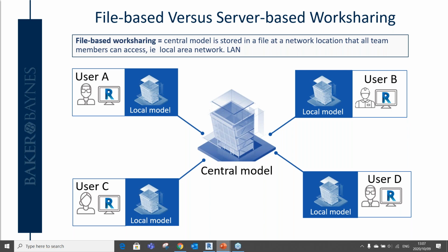When a project team is working on a local area network, also known as LAN, file-based work sharing provides sufficient performance and is actually the best approach to use. Just note that file-based work sharing does not require installation of the Revit server application.